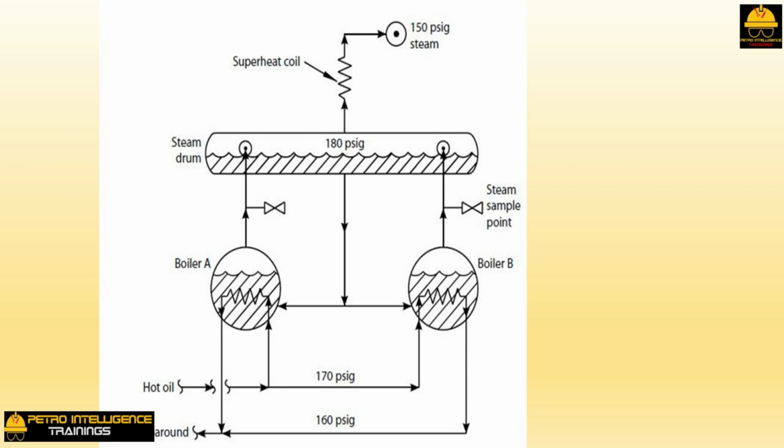It was found that the steam was contaminated with gas oil whenever the waste heat boiler B was in service with boiler A offline. Boiler A was put back online again and the water reappeared in the fractionator as it had on the 4 prior occasions. However, we now had boiler B isolated, but left boiler A online, with no resulting oil contamination of the 150 psig steam and with no water contamination of the gas oil pump around. A tube leak was found and fixed in boiler B, and then boiler B was also returned to service and the full unit charge rate was restored.